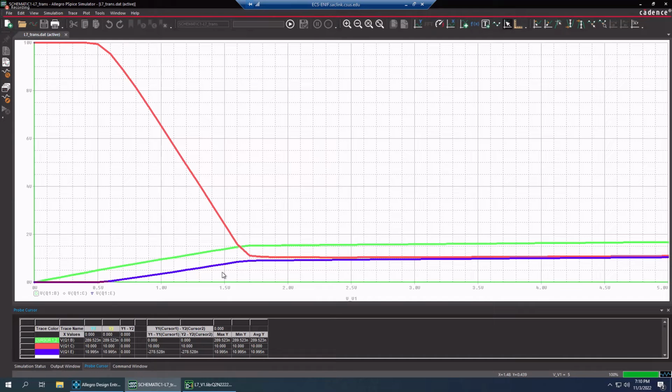That's telling you that the transistor is basically open circuit. So there's no conduction going through it. It's basically open, and so the collector is being pulled up to 5 volts. So what we see is that we've got some current coming in, but we've got to get to a certain threshold before that thing turns on. So it's in cutoff. Then it goes into the forward active region, and then it flattens out and goes to saturation.